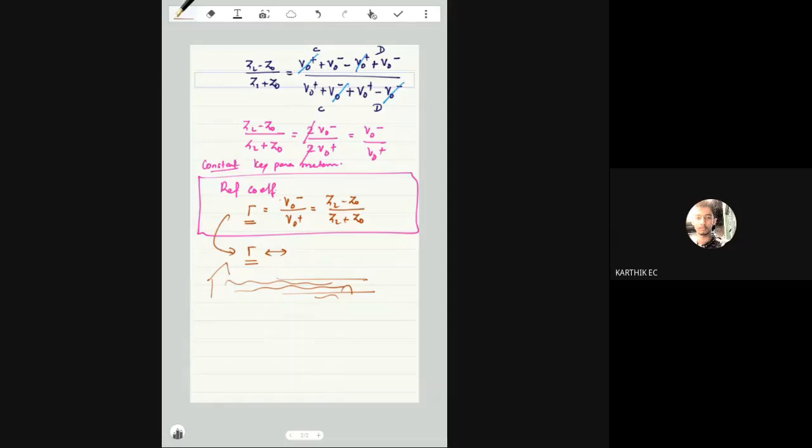So in the transmission line I don't want this reflection. I'll try to remove all the blocks in the canal and stones which are blocking the pathway of the water, right? Similarly, this quantitative measure of how much reflection is happening, I can measure by using this quantity gamma. If you observe closely, this is the ratio of the reflected voltage wave divided by the incident voltage.